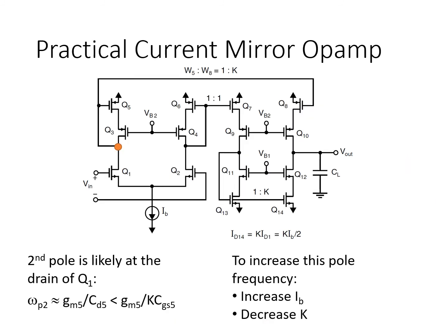So again, in general, in single stage op amp design, there's two possible scenarios you could face. One is where you're constrained to very low power compared to the load cap that you're trying to drive. In that case, you're most likely completely dominated by the pole at the output node.